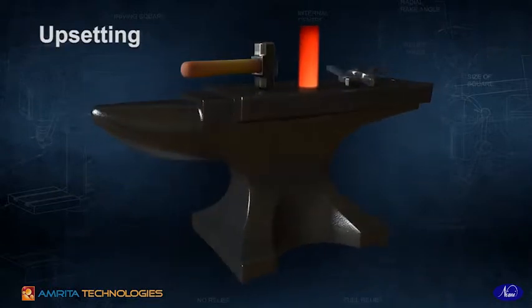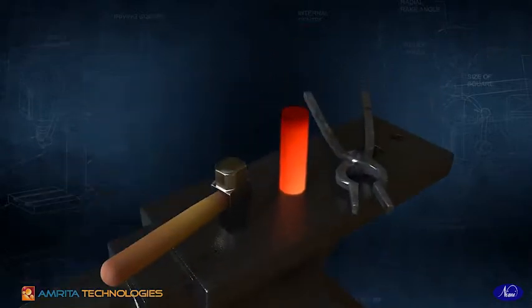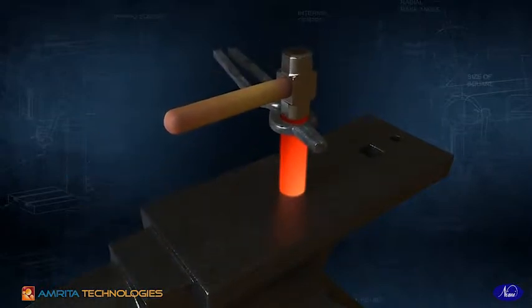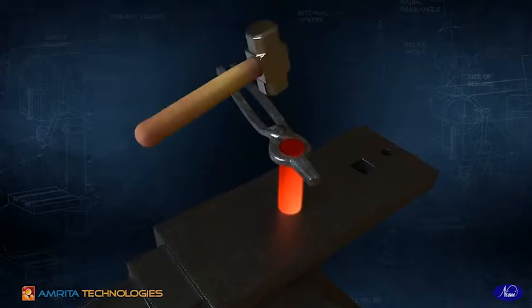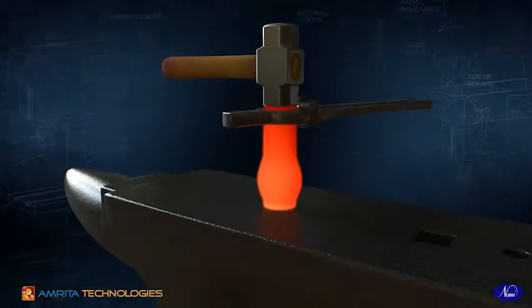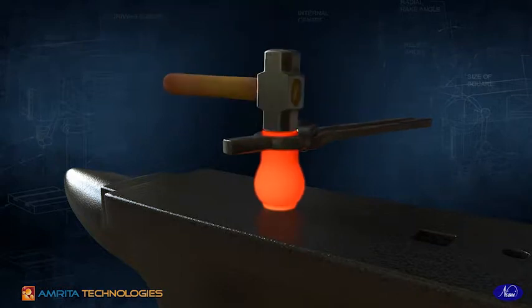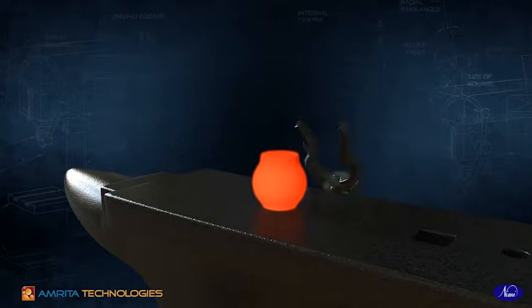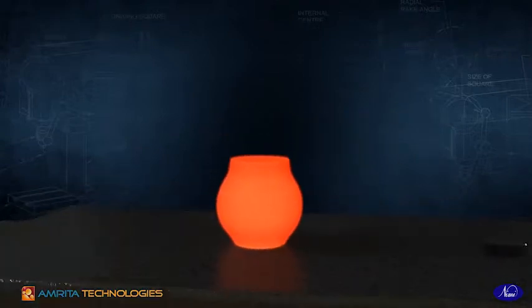Upsetting is a process of increasing the cross-sectional area of a work by shortening its length. One of the simplest methods of upsetting is to place the article on the anvil and hammer it directly on the upper end. The effect of the blow has a great influence upon the shape of the work.